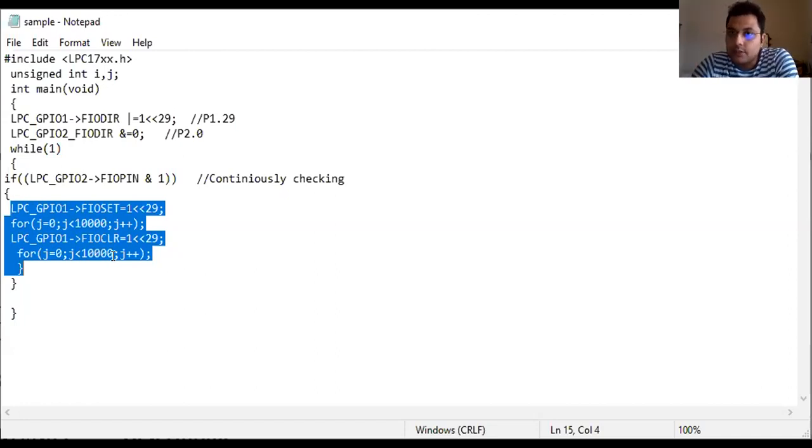You can use interrupts for that purpose. How can you use the interrupts? Now here, instead of this if condition, we will use some external interrupt. That external interrupt pin, obviously some pin we have to configure as an external interrupt pin. The system will take care of it. You don't have to write that thing in your code. So the system will take care of that.